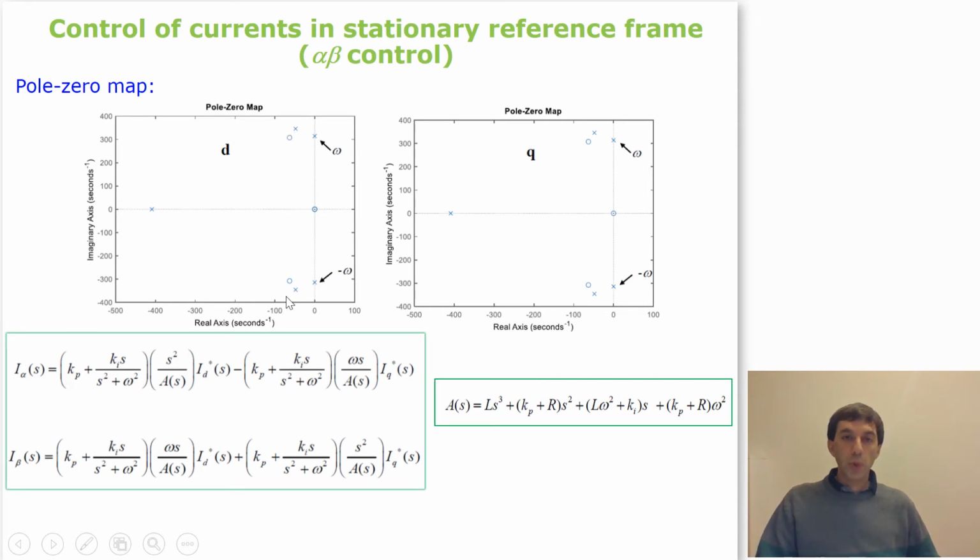So these three poles are the poles that are extinguished at the steady state. So they are the transient poles, the ones that are multiplied by the exponential terms, while these two poles are the responsible for the steady state.